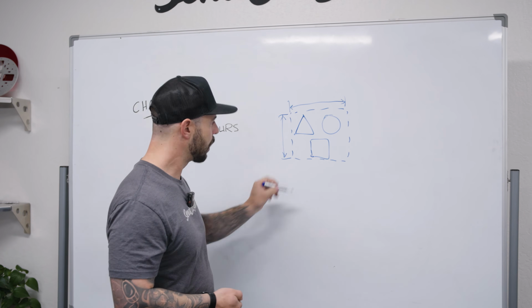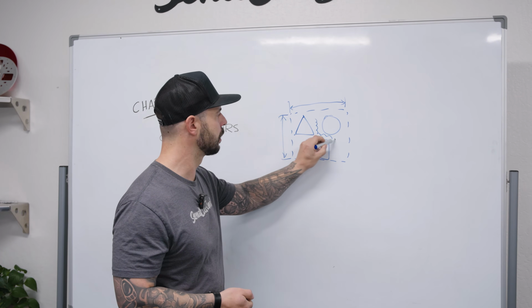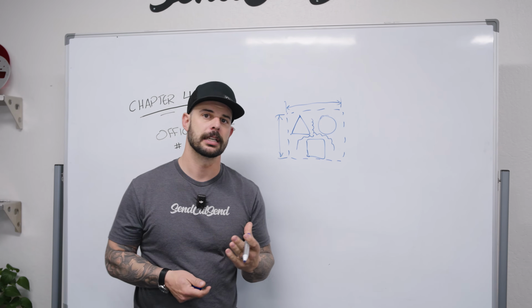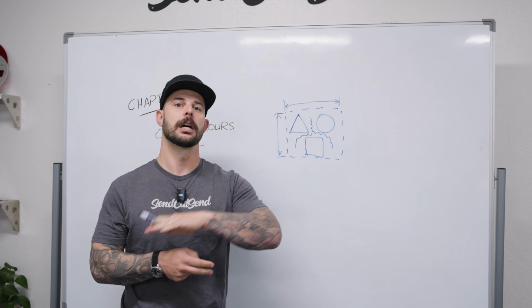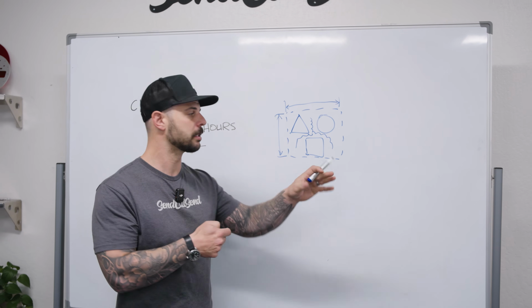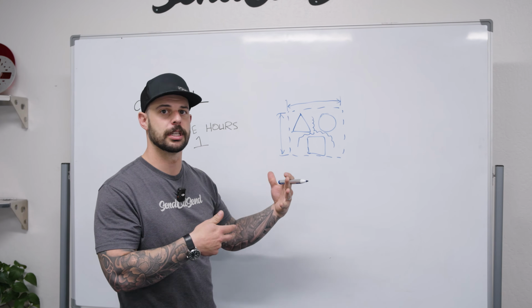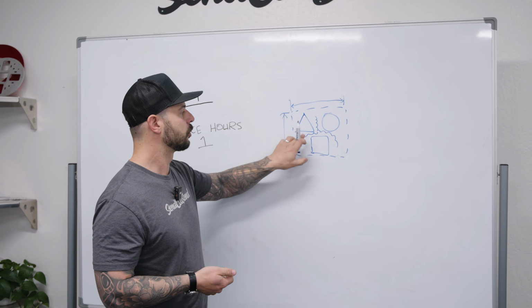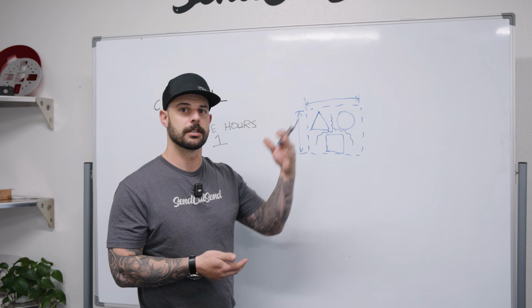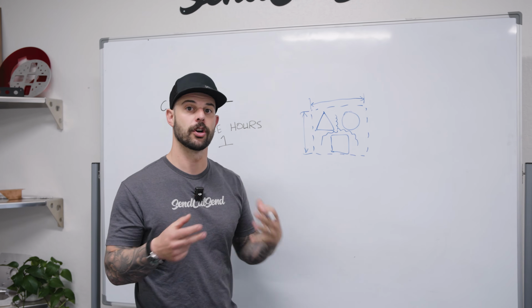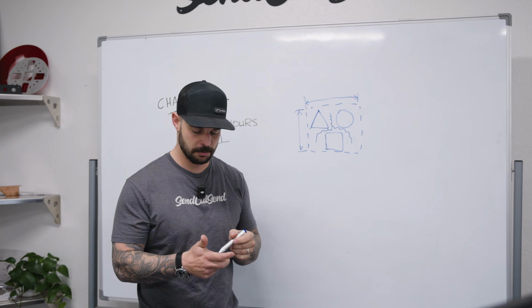The second thing is that we can have a ton of space in here that we maybe didn't nest correctly. Manufacturers like SendCutSend are going to nest your parts among other people's parts, and that's going to end up having a better yield than what you're producing on that nested DXF. So you can actually increase the cost of your parts artificially here, and the better way to do it is to have individual parts, so you're only paying for the material that you're using.